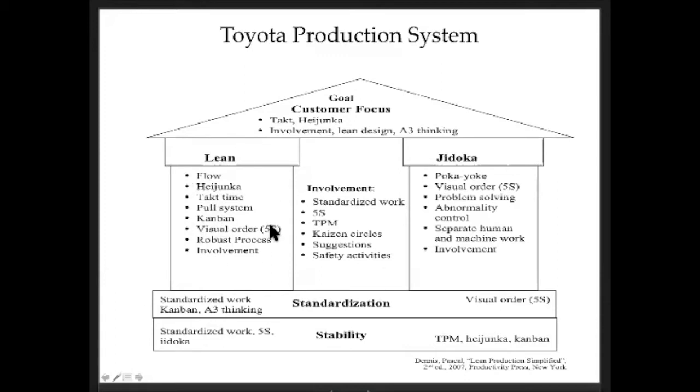There are certain concepts that come under lean systems, and they are used to make a given system go through this kind of lean approach of managing it. And then Jidoka is mistake proofing. It's a way of managing the process so that you avoid mistakes, because the process does not allow mistakes to pass through. It could be by creating systems or parts within a manufacturing context that always fit in a certain way, and any other way, if you try to fit it, it will not, and therefore it's mistake proof by design.